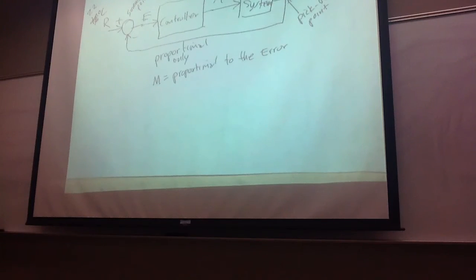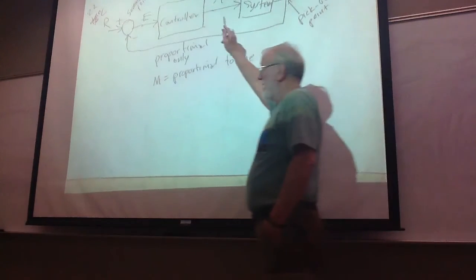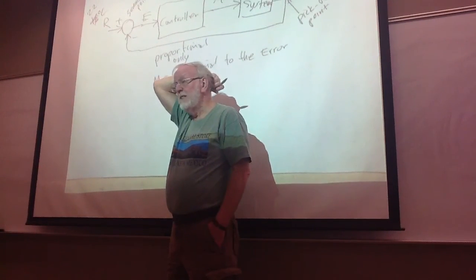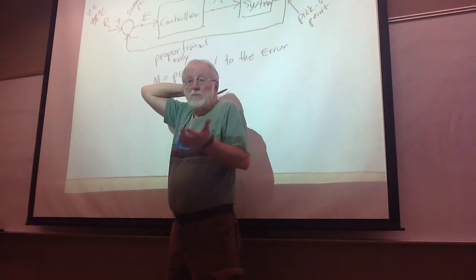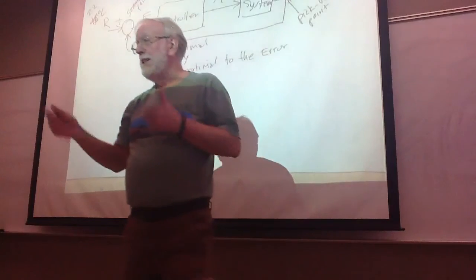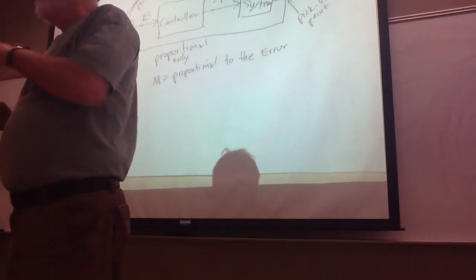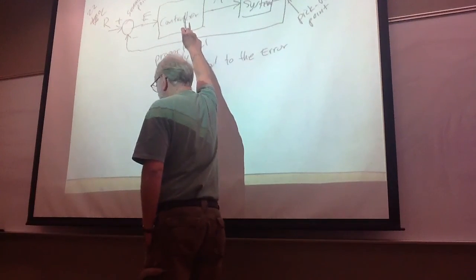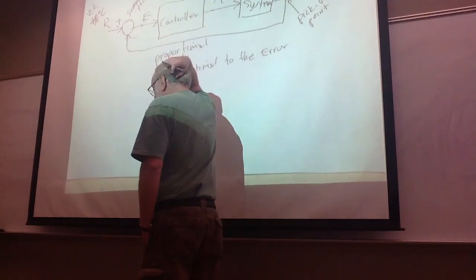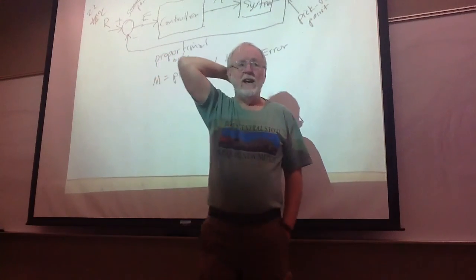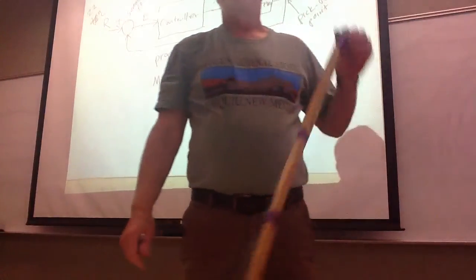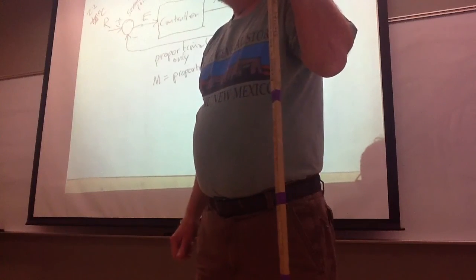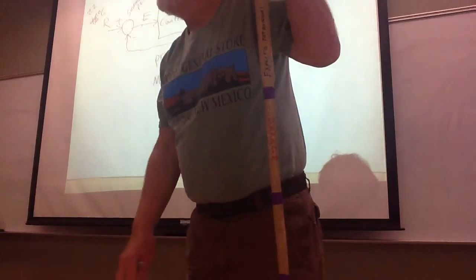And the control engineer, Kc is always positive. Oh, I shouldn't have said that, because in the temperature system it's negative, but let's ignore that small detail. It's always positive or negative if the slope of the steady-state operating curve goes the other way. But it's always a constant. But there's a maximum value that it can have. Does anybody know what we would call the maximum value that it can have? What is the maximum value of the controller gain?